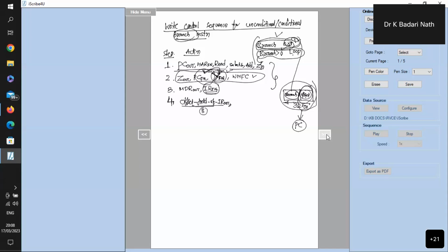Now, what is the A operand of the ALU? It is already available in Y in, written into Y. The only thing is I should be able to instruct the multiplexer to select Y. Select Y means the contents already in Y come to the A operand of the ALU, and then addition is performed.